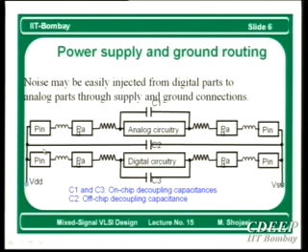What does it mean? Suppose this capacitance is very large. It means that in DC it's open, in AC it is a short circuit, right? Therefore, in AC, VDD and VSS are the same. When we say they are the same, it means that these two will follow each other. And that is enough for us, right? We want two rails whose DC difference is a constant value. Because if VDD increases, VSS also will increase by the same value, because there is a short circuit.